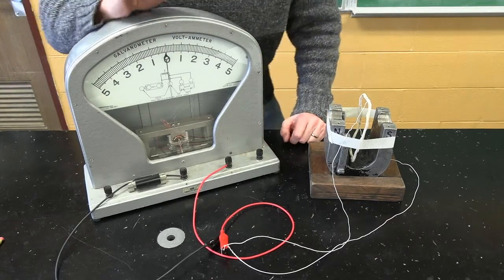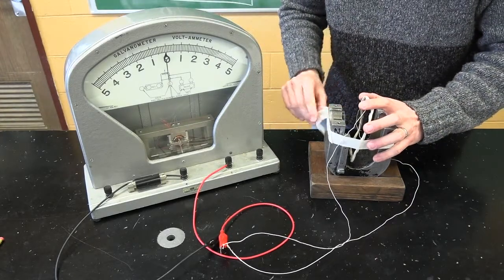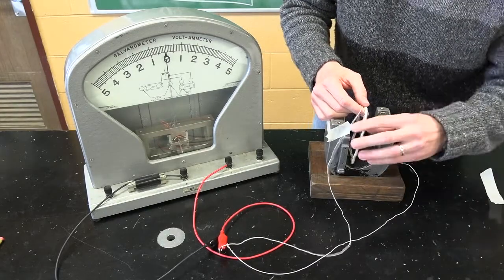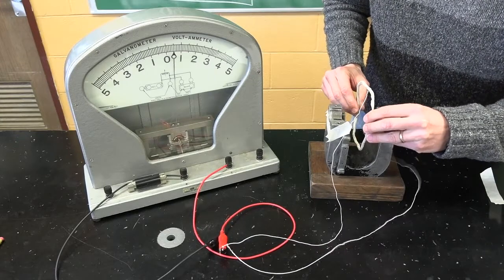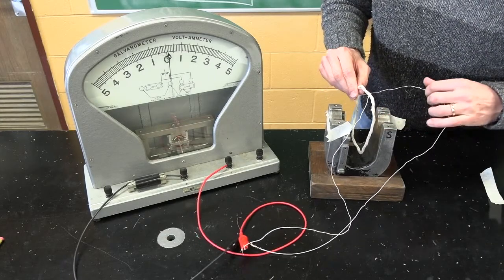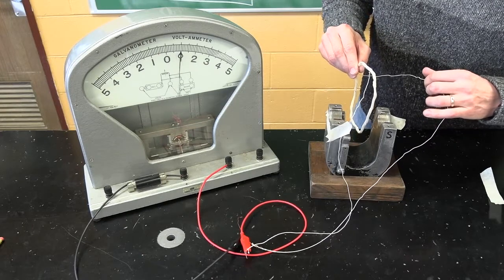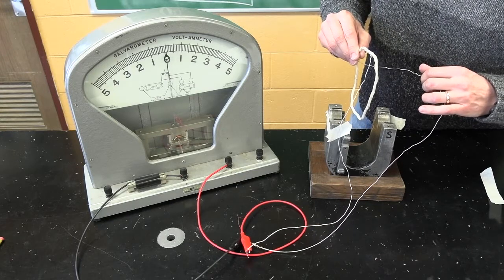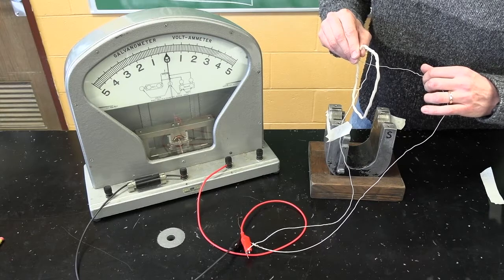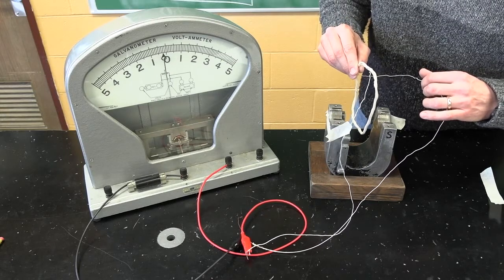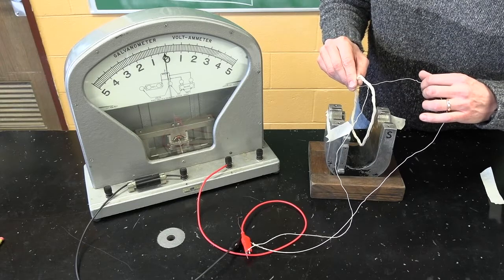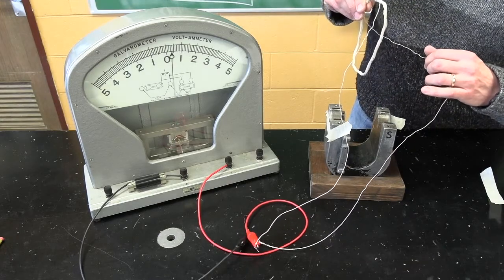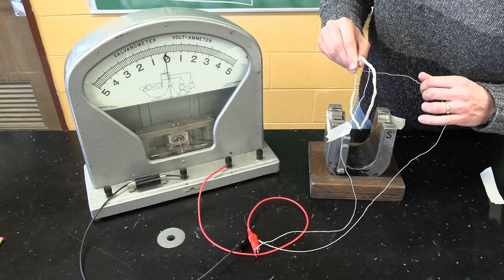So what is it that creates the voltage and therefore electricity? I'm just going to get this tape out of the way, and watch what happens when I start moving this upward. Oh, it's tangled up. I'll start moving it upward. You see the needle deflect while it's moving. As soon as I stop, the needle goes back to zero. So only while there's motion is there a deflection. Same thing going in. Moving, I get voltage; I stop, it goes away. Move it some more, I get voltage; I stop, it goes away. Only while I'm moving it do I get a deflection. As soon as I stop, the voltage goes to zero.